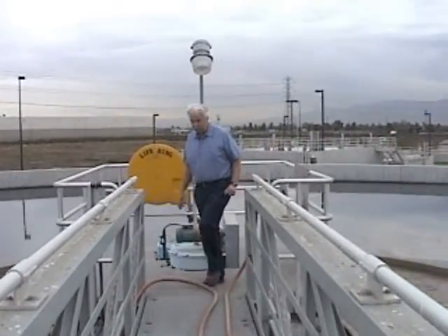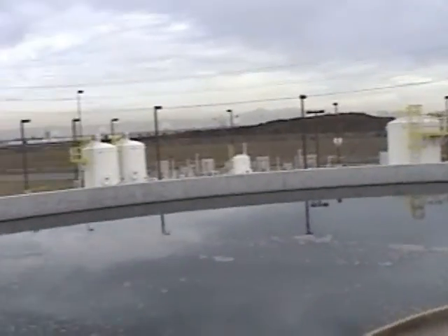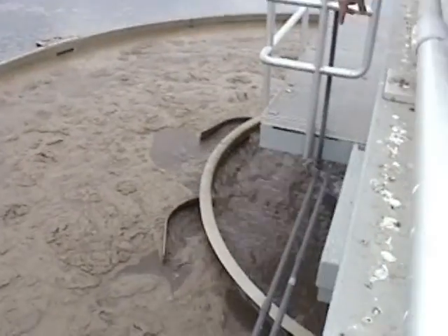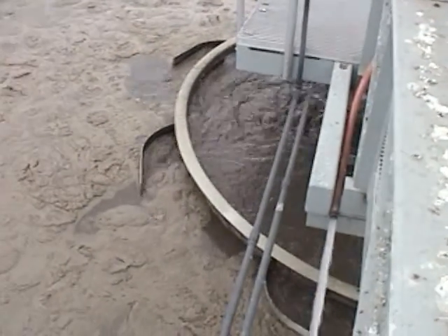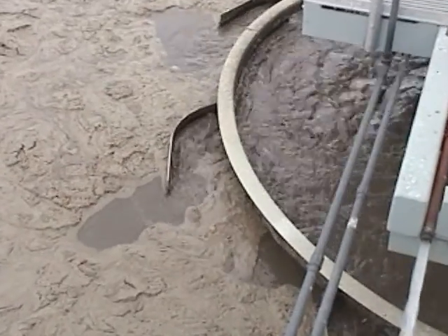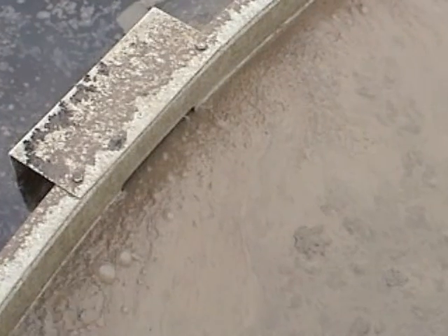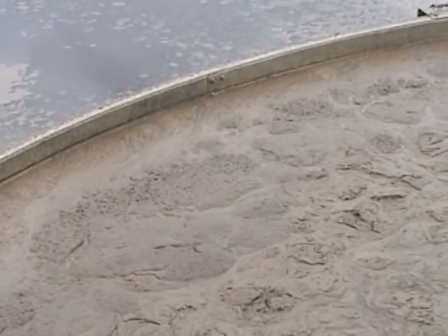The flow from the aeration basins comes up through the center of this secondary clarifier, and you can see it being fed up through here. It's hitting this baffle, and then these deflector plates spread it around through this ring around the outside, which basically is trapping a lot of foam. There are little ports here which allow it to be released onto the surface, but not all at once. It's kind of evenly spreading the mixed liquor around the clarifier. It comes up through the center ring right here, and then out through these ports. This is basically a scum baffle too.